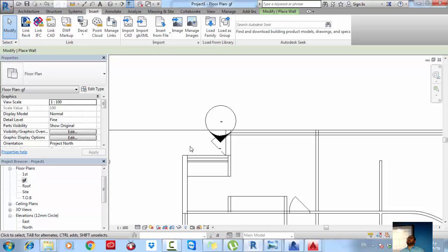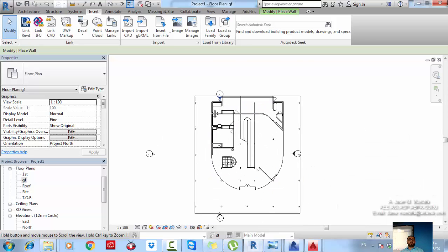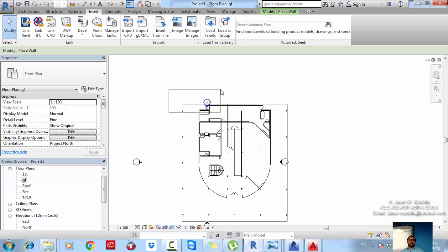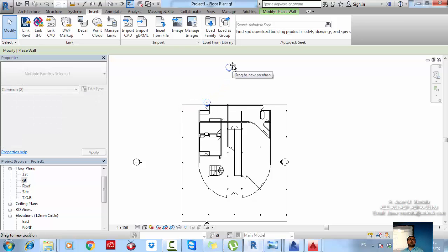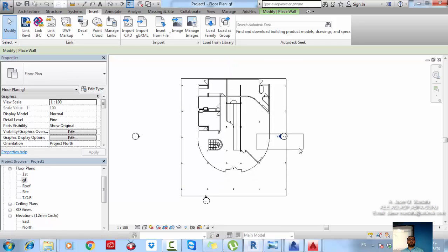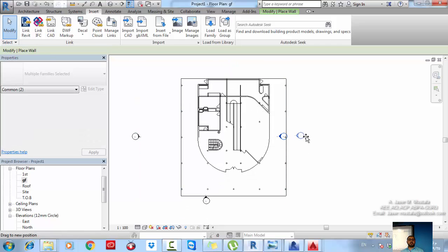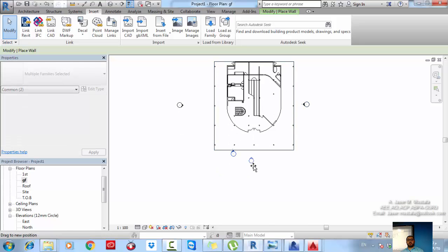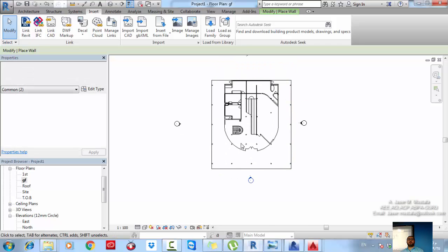Fine. If they are not the units and you are not importing the right scale, you can just import it and rescale the plan to get the correct dimension. Then you can proceed modeling. Fine. Now I have the plan here. Always make sure that these signs, the elevation signs, are away from your model, because it's only viewing the things in front of the sign. If anything is behind the sign, it will not appear in the elevation. Now I have moved these signs so I can view all the elevation.